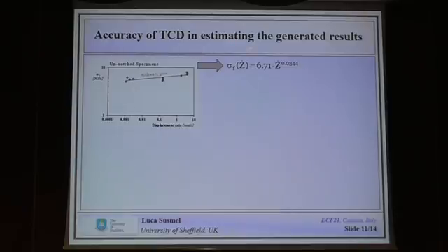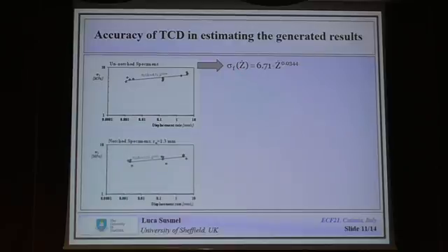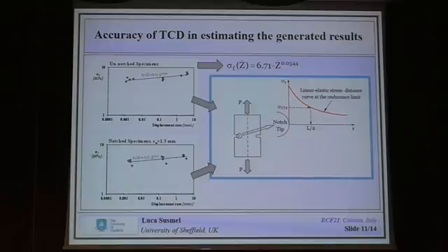This is the function we used to calibrate the failure stress. We used the sharply notched specimens to determine the red curve we need to calculate L for any given value of the displacement rate. We calculated L for different values of the displacement rate, and we got that the L value was constant and equal to 4.8 millimeters. But the average distance between two adjacent stones was about 4 or 5 millimeters.